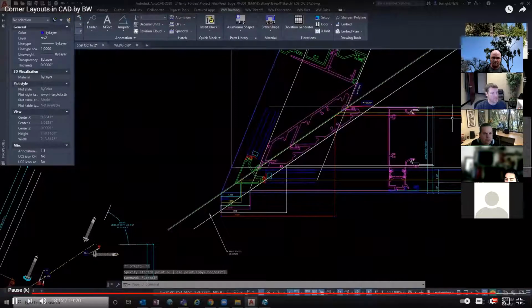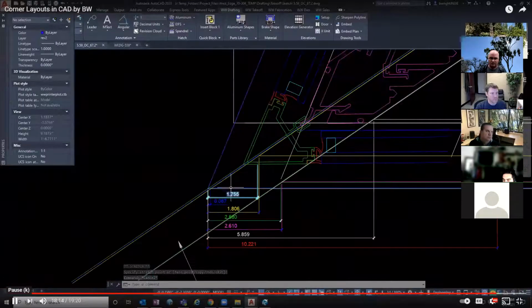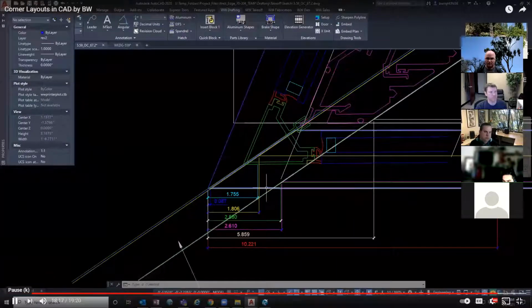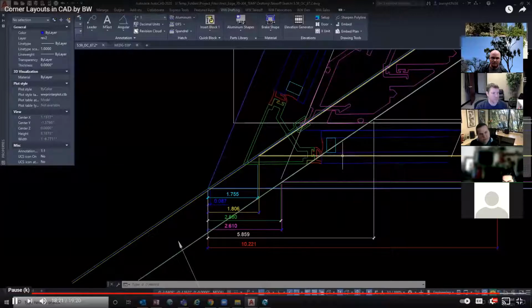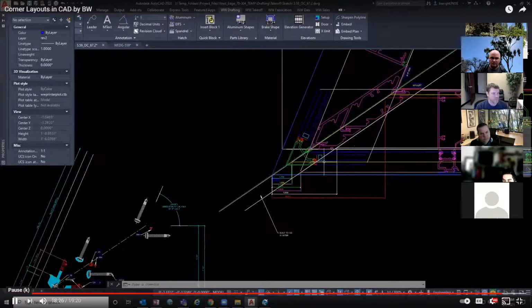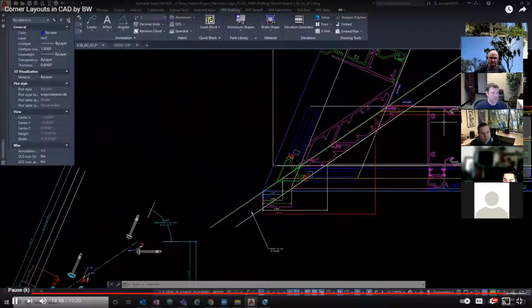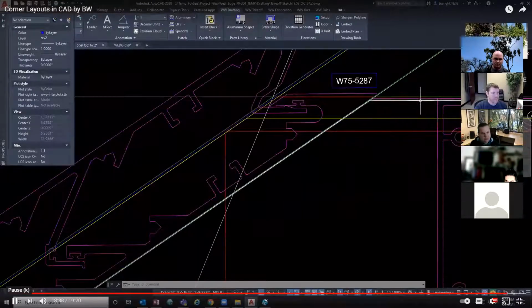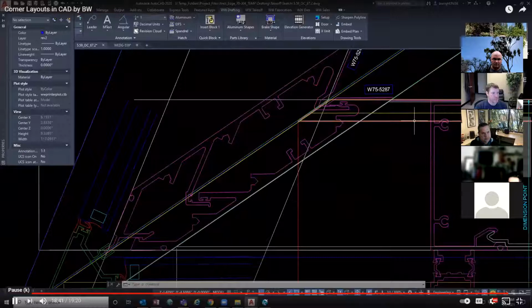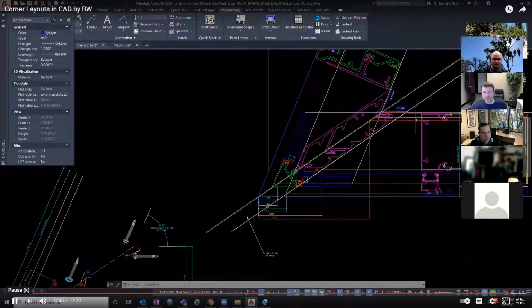As I track through these polylines, I should have the face stop offset 1/32. The sill track will be offset 1/16. The horizontal members will be aligned with the vertical daylight. The head member will be 1/32 short of the vertical daylight. And the drive-on stop will be 1/32 short of the center line.